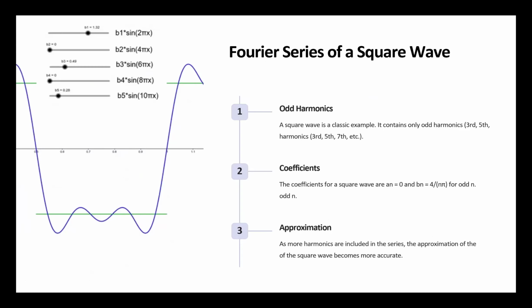So if our fundamental frequency is 60 hertz, in PWM, because of the symmetry of the shapes, we don't see 120 hertz, which is twice the fundamental. We only see 3 times the fundamental, 5 times, 7 times, all the odd multiples of our fundamental frequency. This is because of the symmetry.